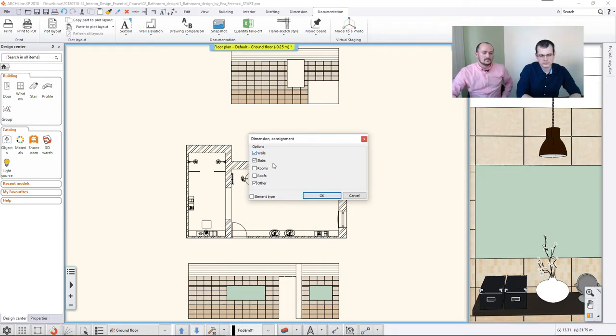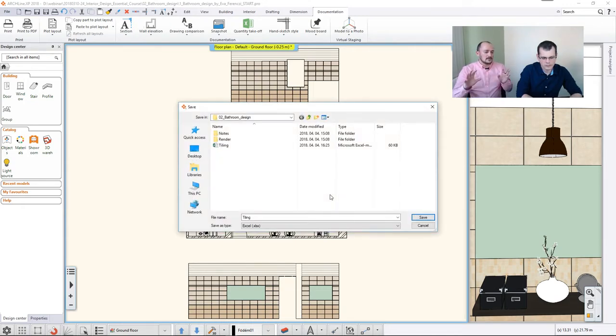If you picked up items from the left-hand side and dropped it on a door surface, for example, and you choose to tile that, you can even do that. But that comes with a few limitations. In that case, other is also an option that you should use. If you tiled roof surfaces, then this is something that you need to turn on. I did not cover these surfaces, so I will just keep going with the walls and slabs. But you can also cover other areas.